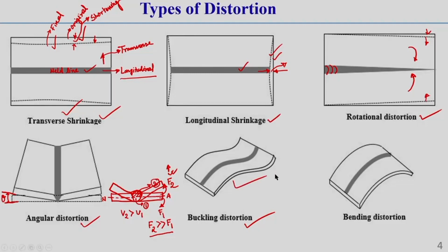So, due to this, generally, a combination of the shrinkage effect, length of weld and thickness of the plate causes this buckling phenomenon. You should always keep this in mind. For a buckling type of distortion to not happen, the plate length, or weld length, should be less than the critical length for that thickness of the plate. So, for different thicknesses of plate, you can use different lengths of weld. You always keep this in mind.